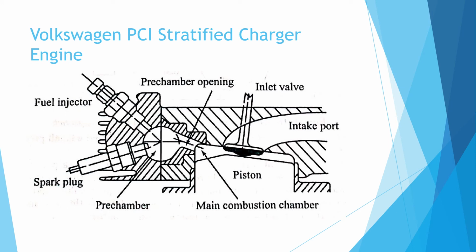The total fuel volume is divided and is injected partly into the pre-chamber and partly into the intake manifold respectively. A relatively rich mixture is made available at the spark plug under all operating conditions.